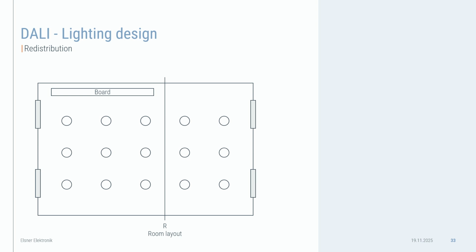In the next step, the training room was split into areas. With conventional wiring, this would require a lot of electrician work to change. With a DALI system, a system integrator can easily set up lamp groups and adjust them to the new room layout. This is very useful for offices, schools or companies where room usage may change. A possible new grouping is shown in the graphic.